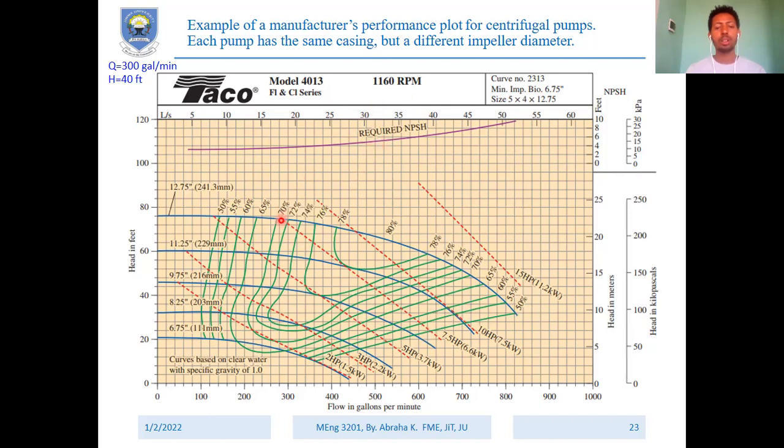For this pump, we can mount these impeller diameters having the same casing. So these can be mounted on the same pump. The problem is, according to the need, the power consumption and the efficiency vary. We have to be careful which one has good performance, which one consumes less energy or brake horsepower. These points have to be considered. So this blue curve is showing the impeller diameter.